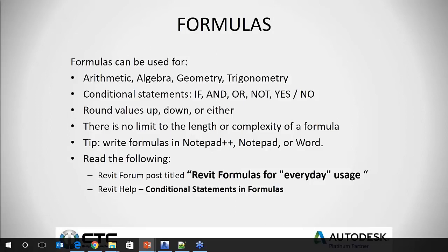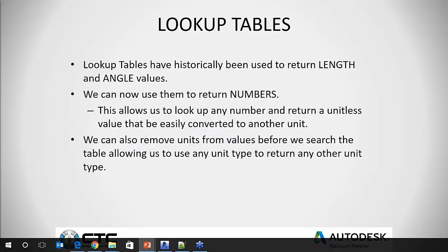So formulas can be used for arithmetic, algebra, geometry, and the conditional statements are typically if and or, not, and yes and no's. We can round our values up or down. Generally, if I get below half a GPM, I will force it to round up to a half a GPM.